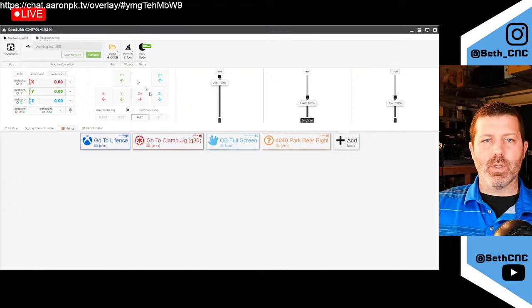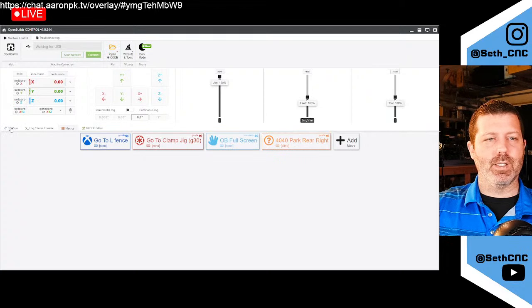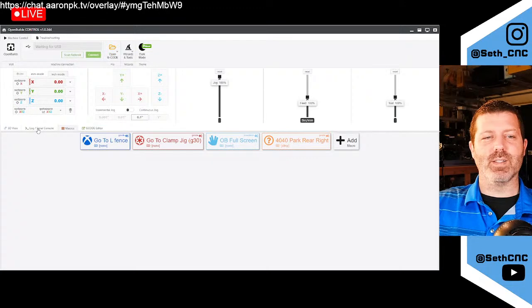Yeah, I guess we can go through the other one, the pop-up for having the Z hide when you select the larger jog amount. And then it's going to hide these buttons. That's a good one to hook up if you're worried about crashing it, right? If you oftentimes click these buttons by accident and end up crashing your Z into it. Hopefully you've got a limit switch there, or you've set up your soft limits to do that automatically. But anyway, we've gone through setting up a few of those.